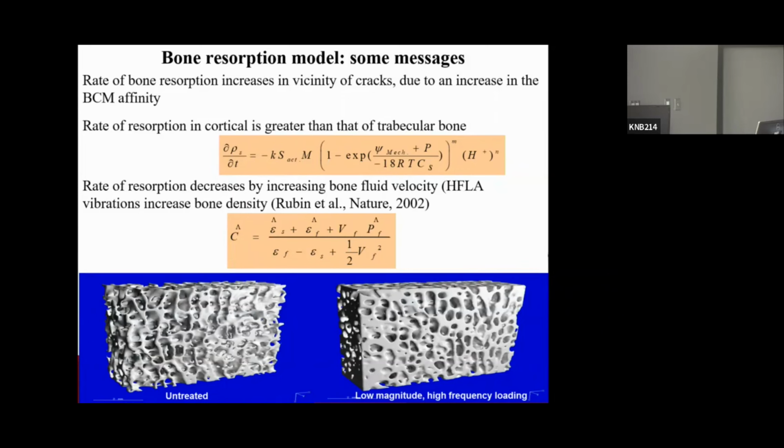Okay. Any question, please? Yes, please. I have a sort of practical question about the use of these remodeling algorithms in implant design. You can correct me if I'm wrong, but I have the impression that I don't necessarily need a very good resorption model to tell if one implant is better than another, because you can look at the stress shielding at the starting state.